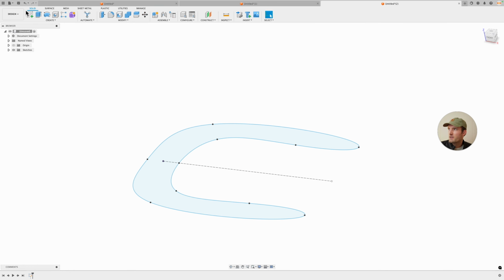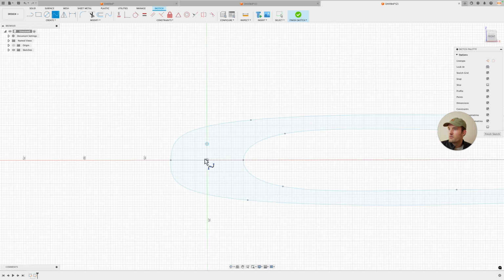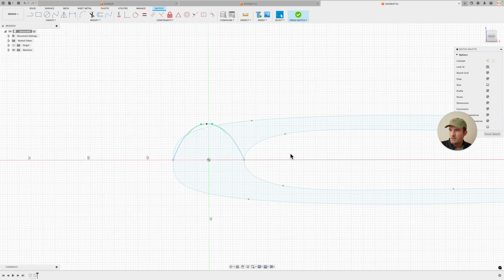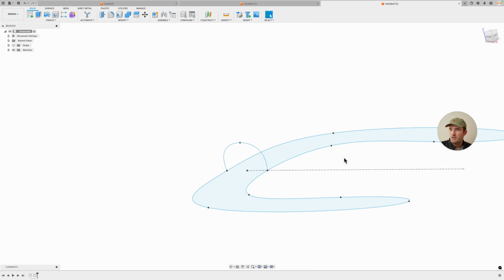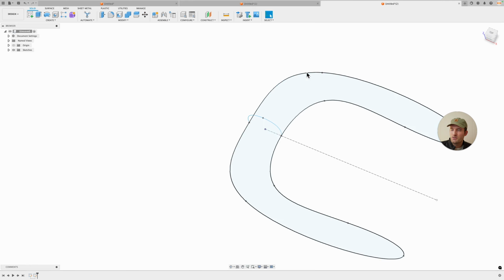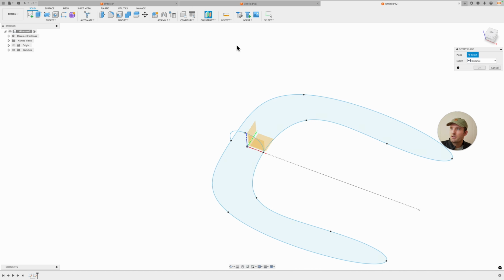And now we're going to make a couple of profiles, kind of like you did with the loft. So again, you might have already done this, but just do profile there. Make sure you don't connect this, because I did that and it gives this method a little bit of issues when you do it that way. Okay, finish sketch. And now we're going to make another plane kind of over here. And you're basically just trying to make a guide for the surface that we're going to make here in a little while. So another plane, let's do